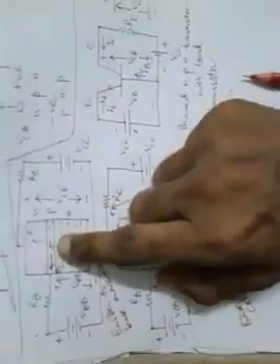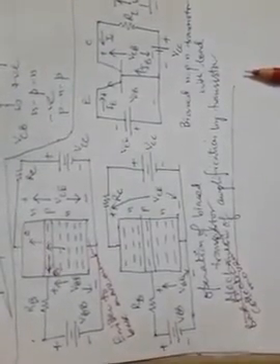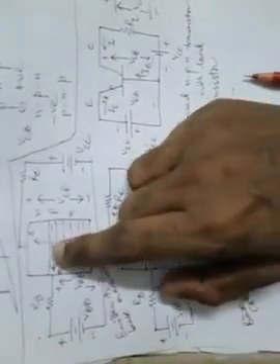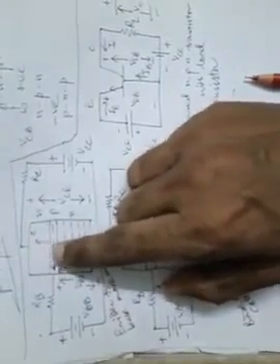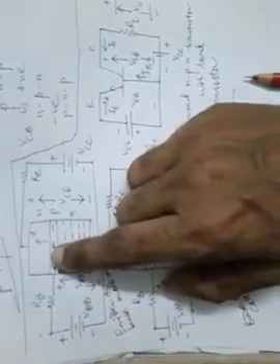This is because of two reasons. First, the base is lightly doped and it is very thin. Because of the very thin area of the base, electrons will be required to stay in the base area for a less amount of time. So there will be less time required for the electrons injected from the emitter side to cross over the base area to go into the collector side immediately, because the area of crossing the base is very small, so it will require very little time.